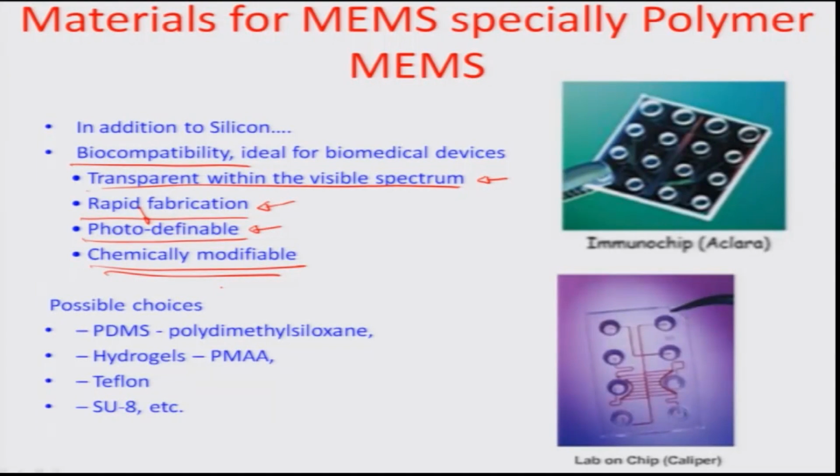Out of all these different criteria for generating an alternate material for doing microstructuring or MEMS work, the possible choices which emerge are PDMS, polydimethylsiloxane, again a very good polymer which comes in two phases, but it reacts and bonds as an epoxy and makes a rubbery membrane, but you can actually microstructure this membrane by making it through a micromolding process.